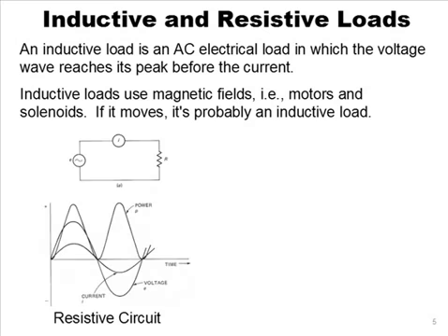This is what it looks like. Here's a resistive load. Now look at this part of the sine wave. Which is your voltage line? Here it is here. Voltage is here. This is amperage and this is power, okay? You see power, I, right here? What happens? They all peak at the same time. That's resistive. That's beautiful. There's no inductance here. Power, amperage, voltage, all peak at the same time.